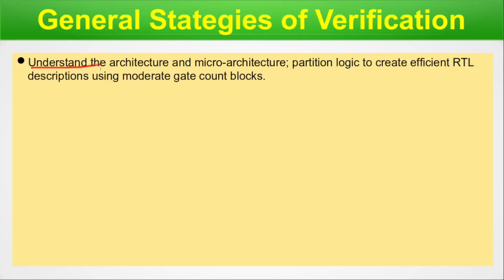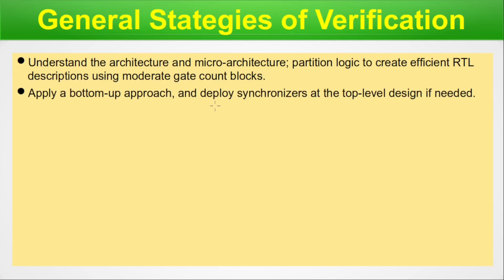First point is to understand the architecture and microarchitecture. Partition logic to create efficient RTL description using moderate gate count blocks. So this is the first strategy that we'll be looking for. Next is to apply a bottom-up approach and deploy a synchronizer at the top level design if needed.